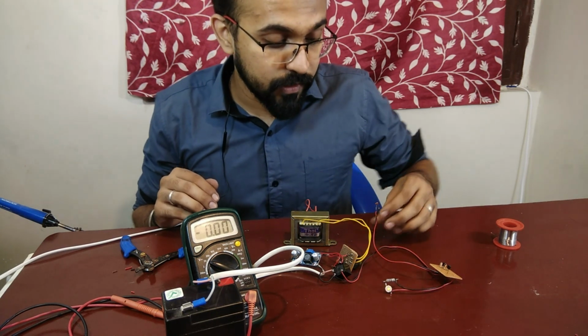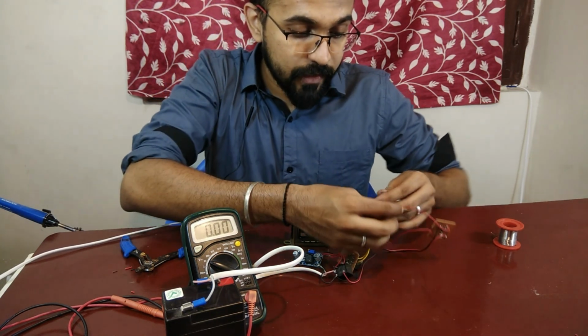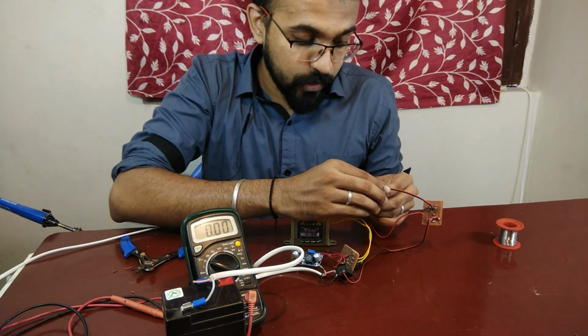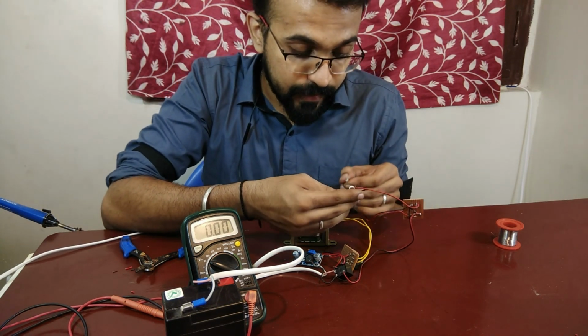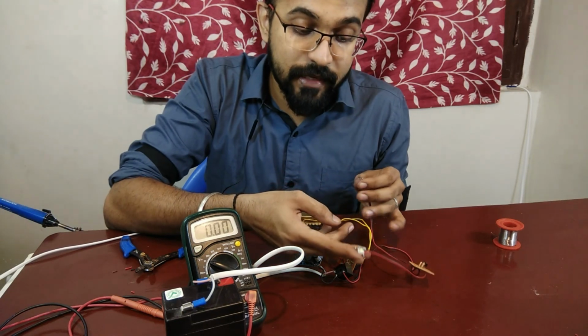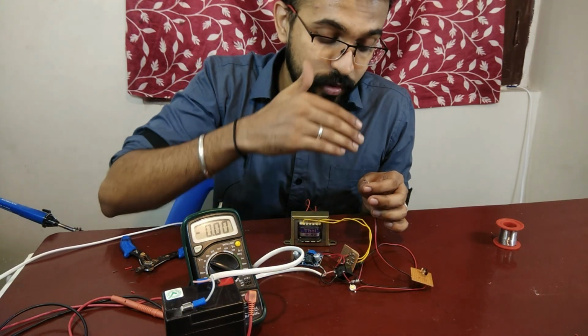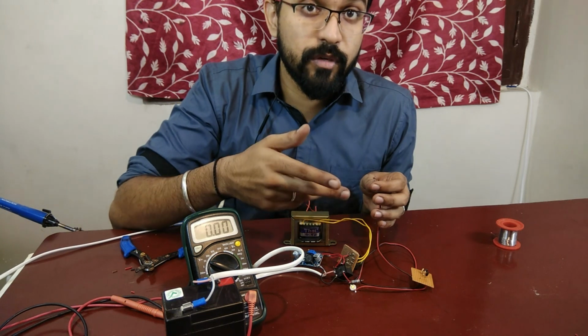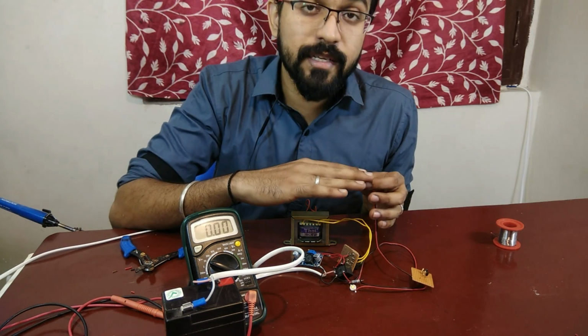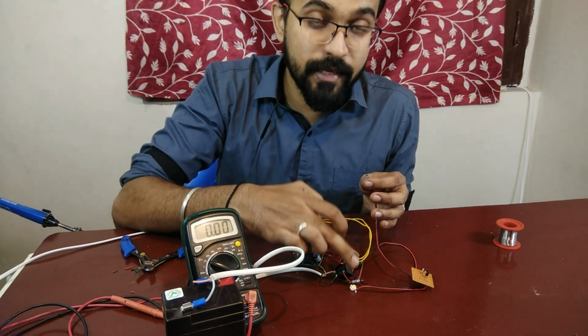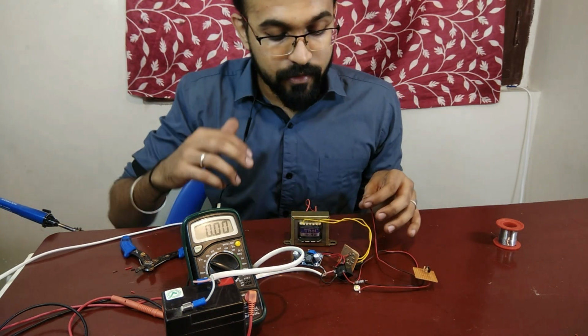So one thing is, we cannot put the LDR where the LED already is. So what will happen is, when we place the LDR directly in line with the LED, whenever the LED switches on, it will feed it back through the LDR to the circuit, and the LED will switch off. So it will oscillate, or it will switch on and switch off automatically. So make sure you place the LDR somewhere where the light from this LED doesn't fall on the LDR.